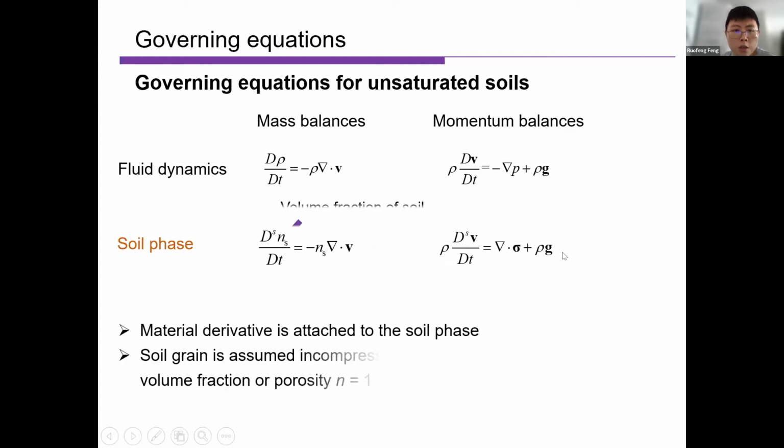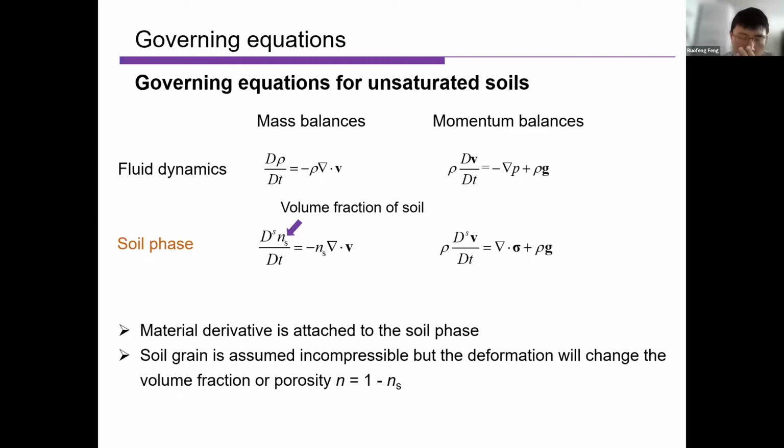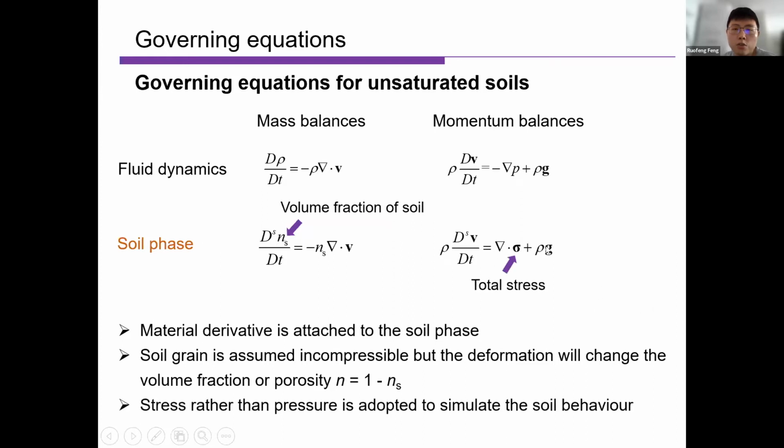And we do not involve density because we assume the soil grain is incompressible, but the solid skeleton is compressible. So we involve the volume fraction of soil, or we can consider it as porosity. And here we use stress, not pressure.